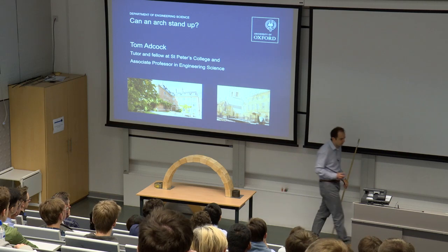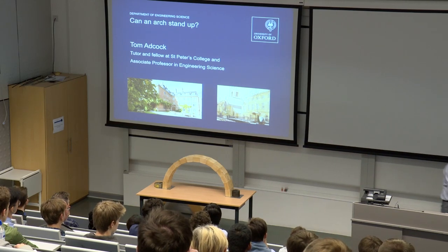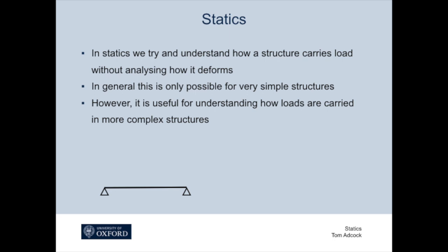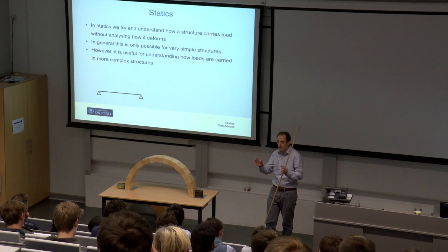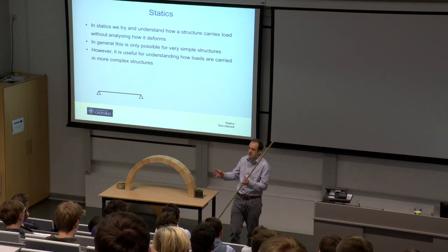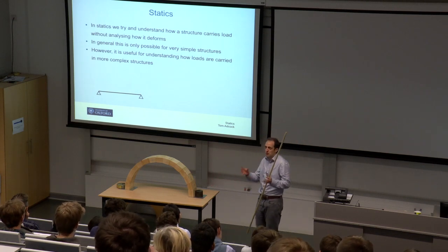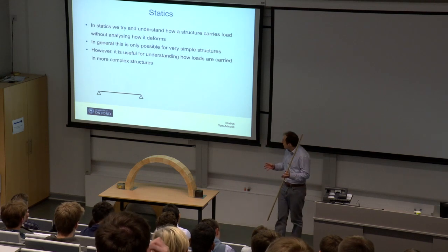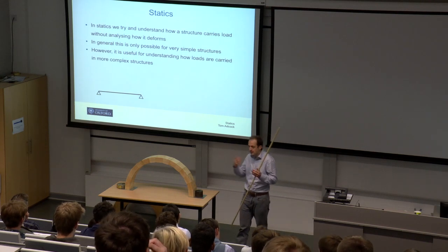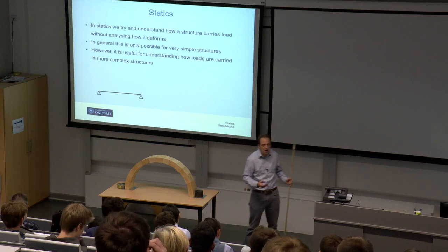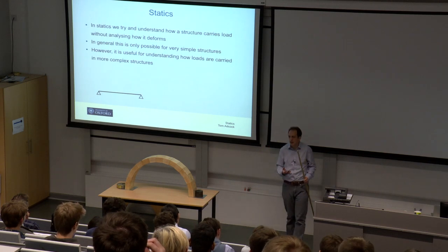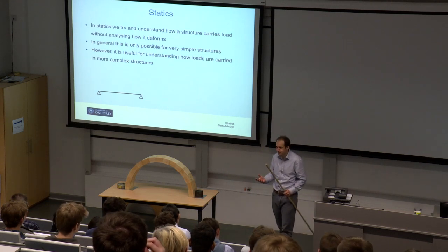So, as I mentioned, this talk is part of a set of lectures on statics. Statics are a class of essentially structural problems. So it may be an arch like this, it may be something more mechanical where you're trying to carry forces from one place to another, but essentially where we want the structure to stay still. And statics are problems where we can actually solve for what's going on without actually having to calculate the deflections in the structure.